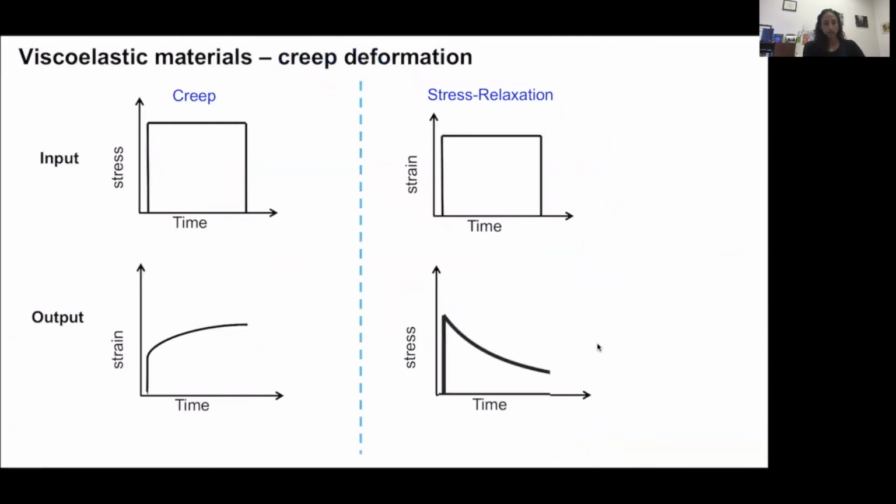So to summarize what we have in terms of our viscoelastic materials and how they actually typically respond in nature, if we look at creep versus stress relaxation, if we apply a force to viscoelastic materials, we typically see a response where there's an initial elastic response, and then we have a time-dependent response, where there's a gradual nonlinear increase in our displacement over time.